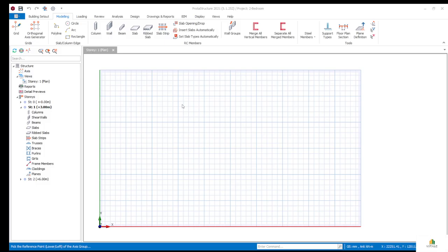So we are done with the direction 1 axis. That's the one that's moving in the horizontal part. Let's move on to the direction 2 axis, which is the axis label 1. Then let's delete the 5,000 asterisk 3. Then type 4,000, comma, let's say 3,500, comma, then 1,500, comma, then type another 4,000, right?